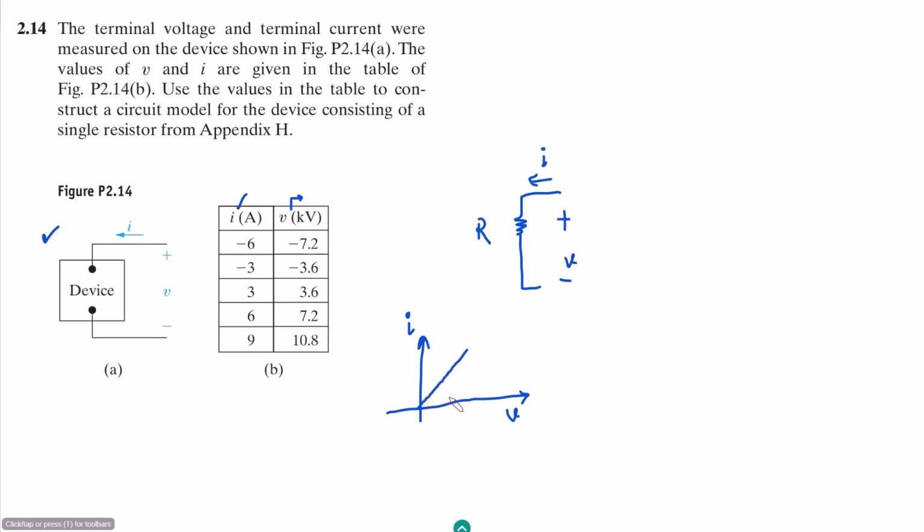graph of it will be like this, and it will be ramp shaped. Okay, and the slope of it will remain the same, which is the inverse of the resistance. From it we can very clearly see that according to Ohm's law, V is equal to IR, and also the value of R here is V by I. Okay, let me put all these values here.